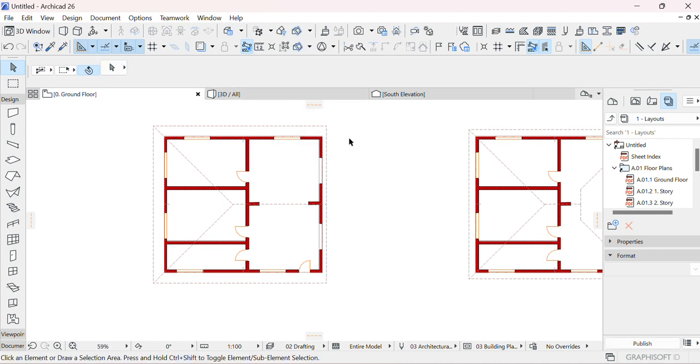there's something that I'm going to teach you which is very interesting. How to pick or to match parameters or to copy characteristics. So for instance, if I don't just want to go on the wall there, I can just use this function here, pick up parameters.